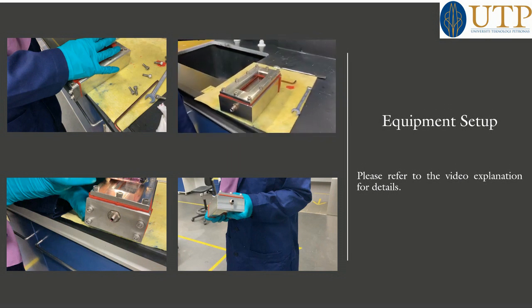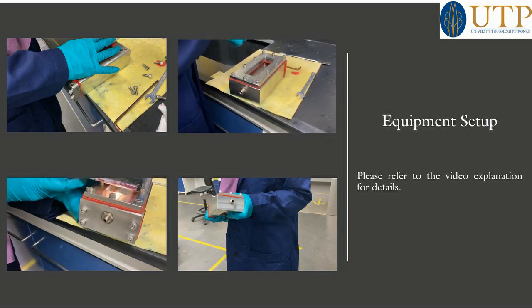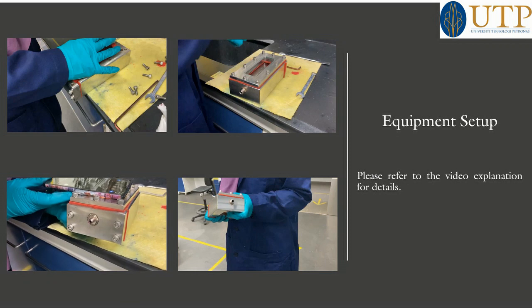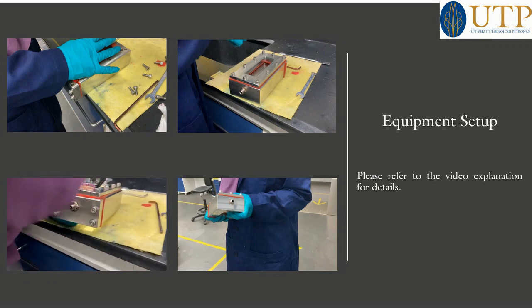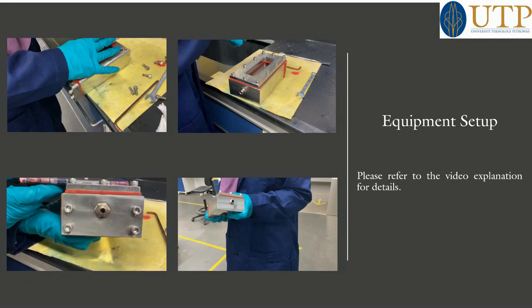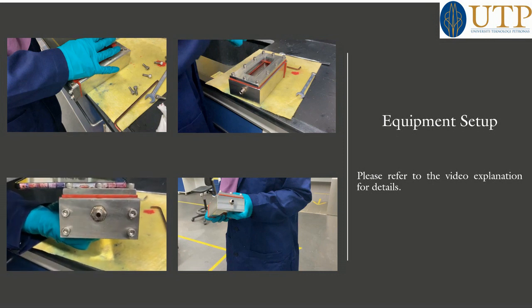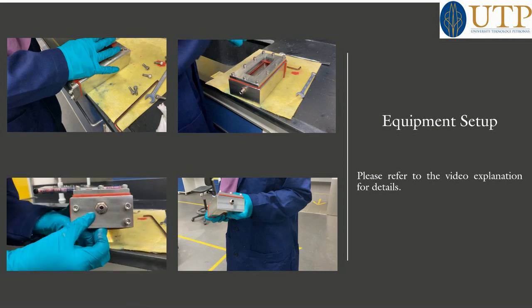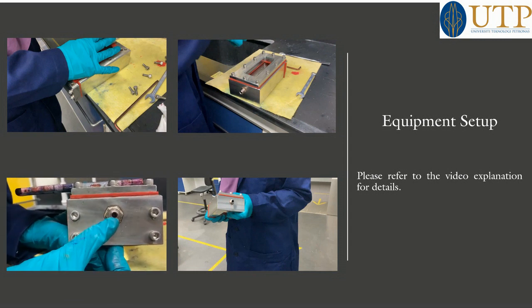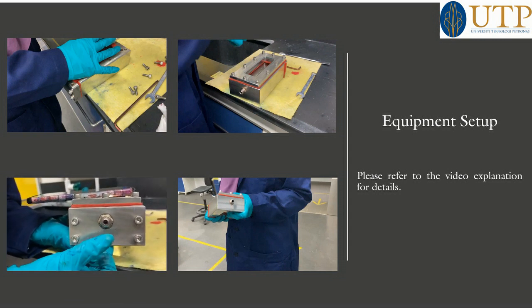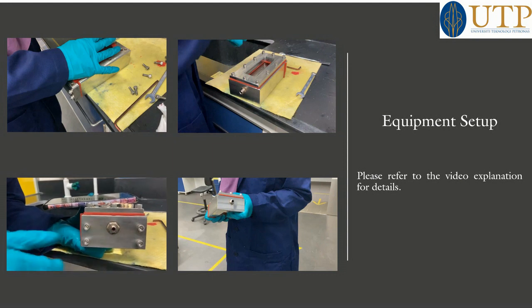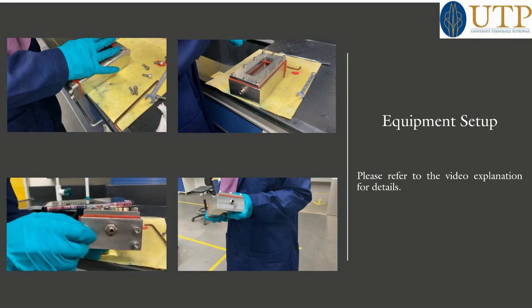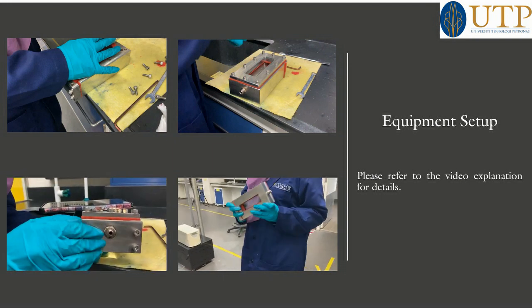And now the inlet, from the inlet you can see there is no blockage. If sometimes a gasket blocks this inlet or outlet, and you see that there is no blockage, then you can start. Otherwise you have to open everything. And now I will install it back.